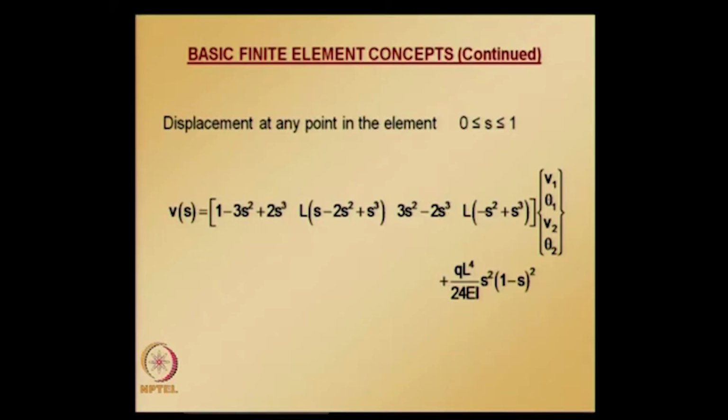The second term is coming from the fixed end solution, which corresponds to the problem of uniformly distributed load over the span. So this is the correction term, and you will not have this term if it is a point load problem, because you do not need to apply this correction term. This formula is coming from the superposition method.